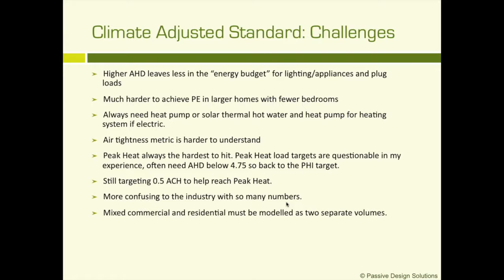And one of the other challenges is mixed commercial and residential, because the mixed commercial is still operating on a primary energy metric of kilowatt hours per meter squared, and the residential is at 6,200 watts per person. We have to model mixed use buildings as basically two separate projects.